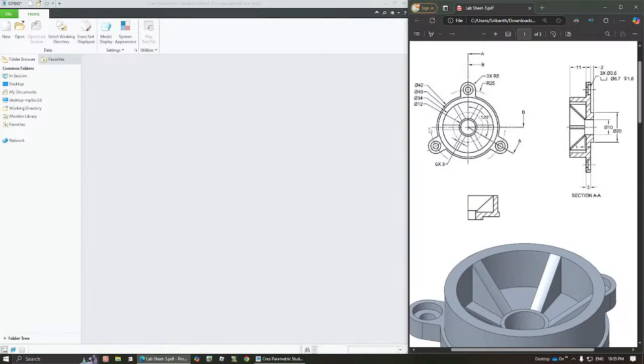So when we see these diagrams, the one thing that we see is this is kind of an object of revolution. So what is the cross section for this object of revolution is the first question that comes to our mind. When we see it over here, it may not be obvious because the section plane is passing through here, and the section AA is passing through here, and this is an aligned sectional view. Aligned sectional view means we can see that the section plane is coming all the way here to the center. After it comes to the center, it is going in this direction.